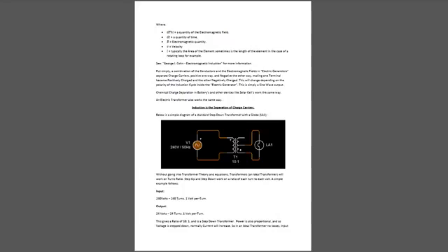Without going into transformer theory and equations, an ideal transformer will work on turns ratio. Step up and step down work on a ratio of each turn to each volt. A simple example follows. Input: 240 volts, 240 turns, 1 volt per turn. Output: 24 volts, 24 turns, 1 volt per turn. This gives a ratio of 10:1, and is a step-down transformer.